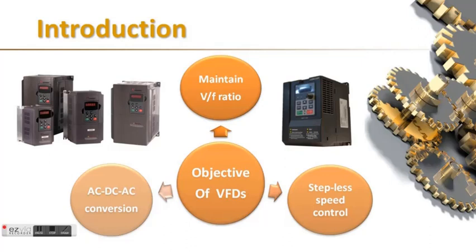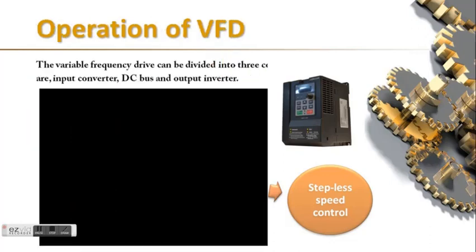It comprises two units, rectifier and inverter. The rectifier converts AC from three-phase into DC voltage, and the inverter converts DC voltage back into three-phase AC voltage. Due to maintenance-free life, induction motors are mostly used in process plants. It is used for step-less speed control of induction motors.